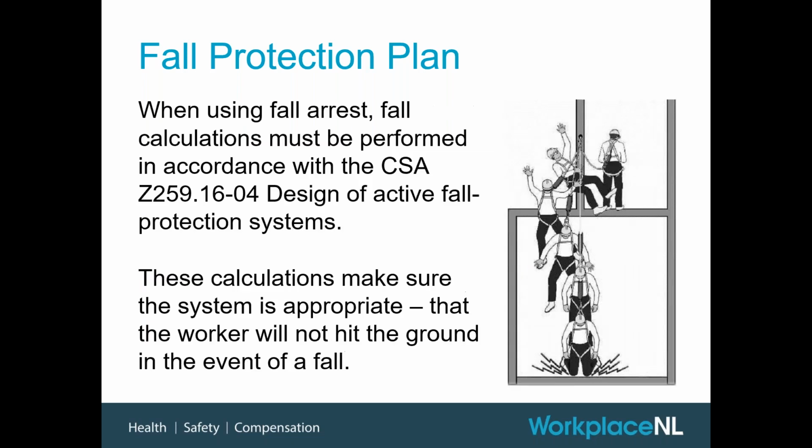doing some calculations. So whenever you're using fall arrest, there are some calculations that you have to perform, and they have to be performed in accordance with the CSA. Sometimes I do come across employers that are using calculations that are supplied by the particular manufacturer that they use. I'm not saying that those shouldn't be taken into consideration, but the way our legislation is designed, the CSA standard, specifically the one I've got listed there on the design of fall protection systems, that really is the one that needs to be the priority.